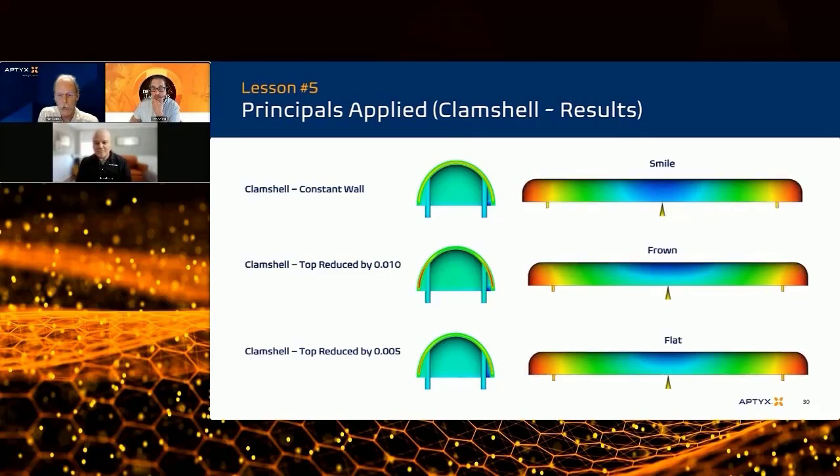Now, what causes magnitudes to be out? There's a lot of things. One of them for sure is the database and how well the material was tested. Moldflow has a gold, silver, bronze kind of rating for their materials. So even if the particular grade we're looking at doesn't have a gold level, we'll find an alternative to run side by side at gold level and try to get a bunch of opinions out of different resins before we make any kind of decisions. But that's a great question, and it's something we deal with all the time. It's the reality of simulation.